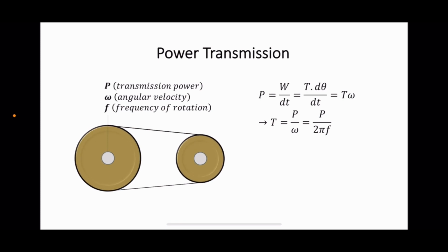Now, knowing the torque a shaft is subjected to, we can easily design the shaft based on the knowledge that we learned in the last lectures. Let us review the parameters in this equation. C is the radius of the shaft. J is the polar moment of inertia of the shaft's cross-section, which can be calculated from the radius C. T is the torque we just determined, and tau allowed is the allowable shear stress of the material of the shaft.